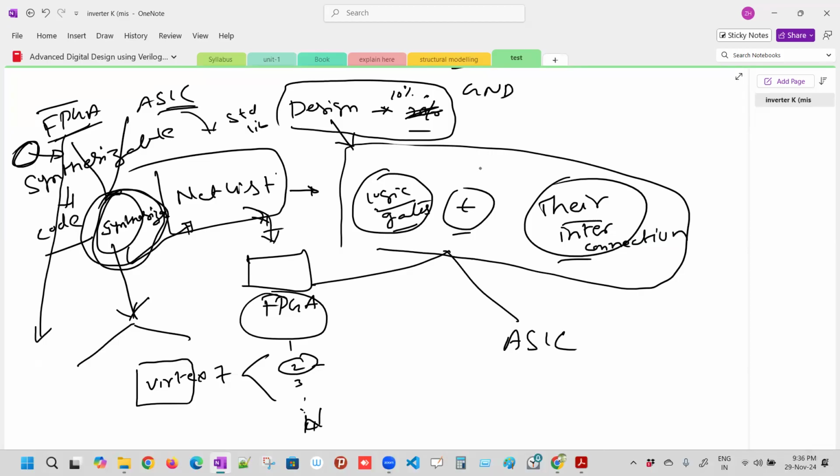And what was the question? The bitstream and netlist difference. Bitstream is related to the FPGA. It's a long process. Like I said, you set the family here and perform the synthesis. Then what is generated is lookup tables, block RAMs, and any DSP slices if you are using them on chip, on this FPGA.